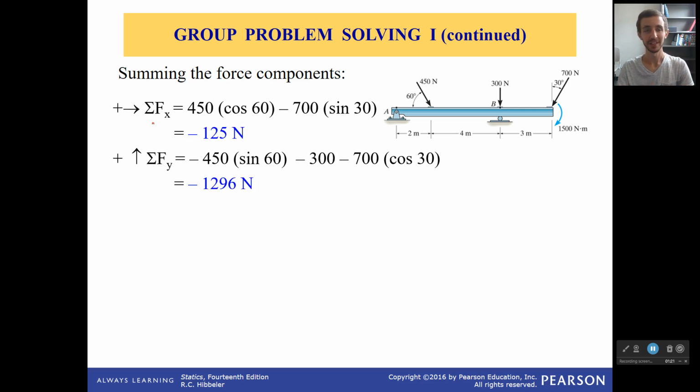So first off, sum of the forces. We have 3 forces, we add all their components together, being very careful about how these angles are specified. So 30 degrees right here. If I write this like this, what can get confusing is that the 30 degrees is talking about that angle right there, which means that I'm using sine of 30, not cosine, to get the x component, and cosine of 30 to get the y.